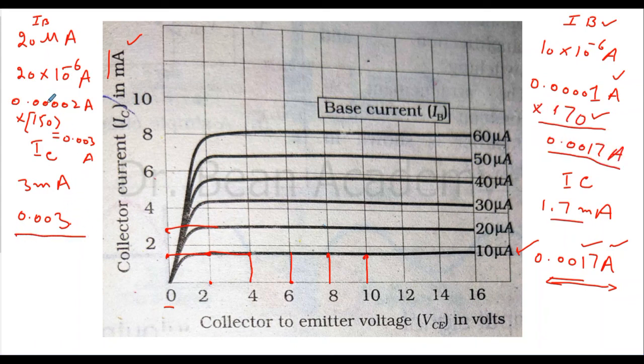So do you know how I calculated this amplification factor, for example 150 and 170 in that case? It is called the beta factor, and the formula is the current at the collector divided by the current you are getting from the base. This is called current gain because it tells us how much amplification you are getting. I mean, you had very little current at the base, but you are getting very huge current at the collector.